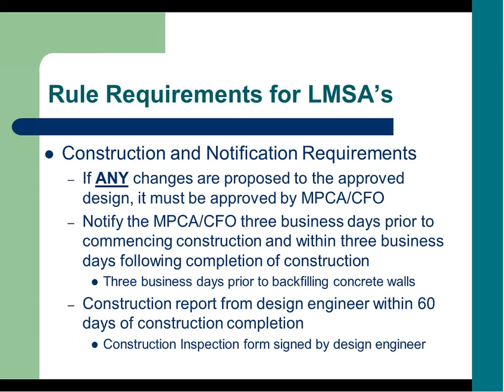Rule requirements for LMSAs, construction and notification requirements. They are required to notify us if there are any changes prior to the change being implemented. They must be submitted to the PCA and approved. Notify the county or the state 3 business days prior to starting construction, before a shovel goes in the ground. And we like to also know when they're pouring concrete, if there's concrete involved, though it's not required. The requirements are 3 business days before start of construction and 3 days before backfill. Also, 60 days after the construction is deemed complete, we want to see those red lines or the construction inspection form from the engineer.